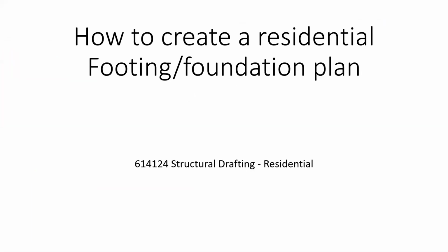How to create a residential footing and foundation. The purpose of a footing and foundation plan is that when they start building the house, in theory, just from that drawing, they could start laying out. Well, they would need a site plan to show where the house goes, but once they know where the house is supposed to go, they could start laying out the footings, building the footings, laying out the foundation walls, building the foundation walls from this one document, which is called the footing and foundation plan.